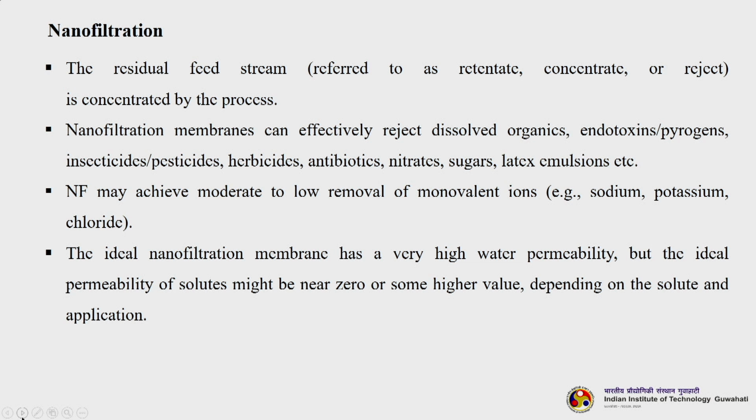Hydraulic pressure is used to overcome the feed solution's osmotic pressure and to induce diffusion of pure water, which we also call permeate, through a semipermeable nanofiltration membrane. The residual feed stream, referred to as the retentate, concentrate or reject, is concentrated by the process. Now, nanofiltration membranes can effectively reject dissolved organics, endotoxins, pyrogens, insecticides, pesticides, herbicides, antibiotics, nitrates, sugars, latex emulsions, etc. And nanofiltration may achieve moderate to low removal of monovalent ions, for example sodium, potassium, chloride, etc.